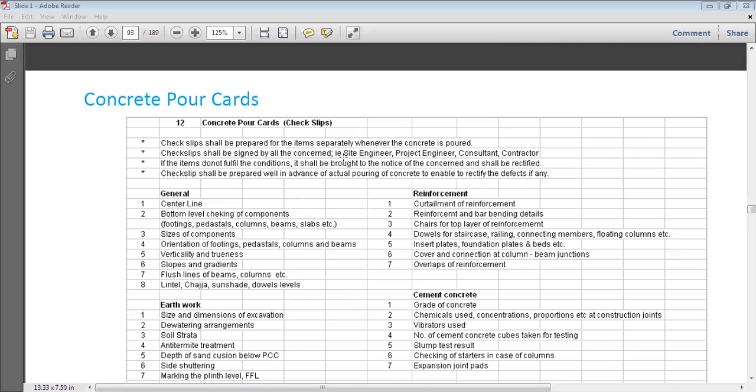Now in the Gauthan region, as per the recent amendments, we have an FSI of around 1.5. Now in most of the Gauthan regions, that means our village areas, that is rural areas, most of the plots are not non-agricultural plots. These are totally agricultural plots. So for such agricultural plots, the farmer or whatever the client or customer, he has the freedom to construct the whole area. 1,000 out of 1,000 square feet he can build, because it's agricultural land. And if the owner has his own land, then he has the freedom, he can build it in any fashion.